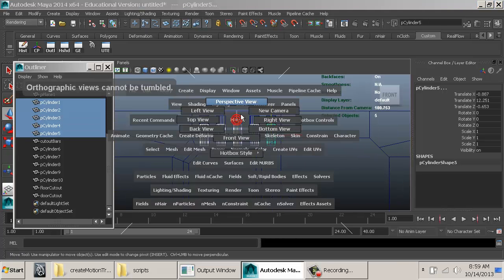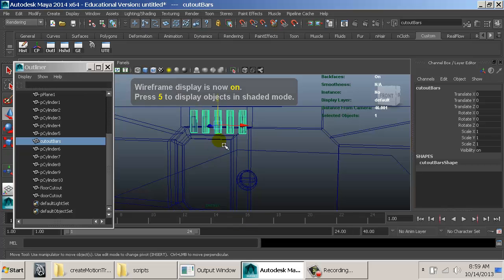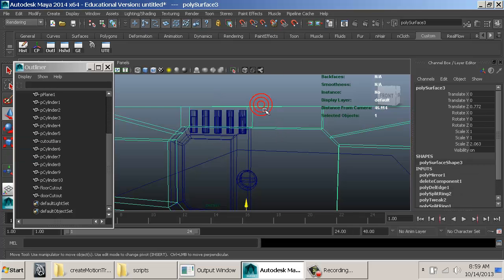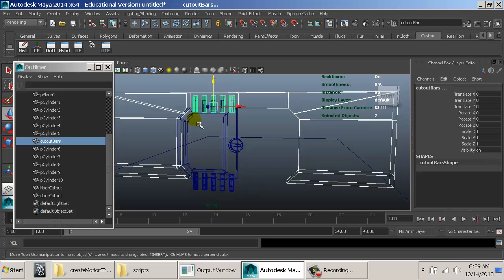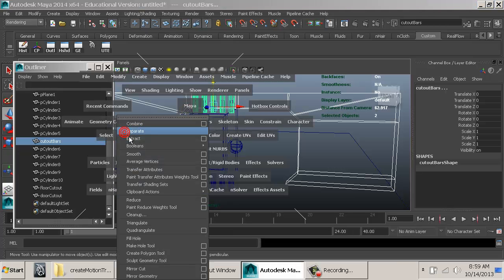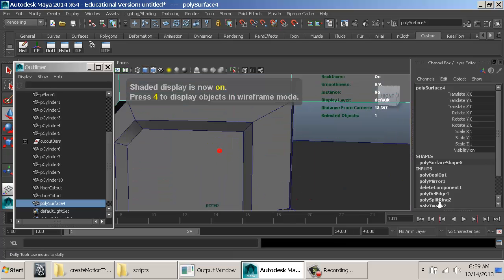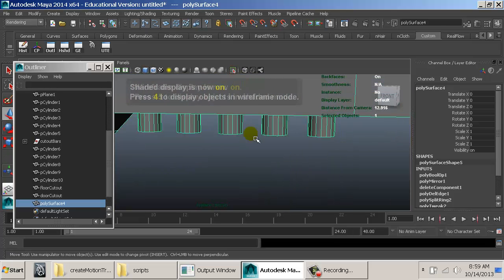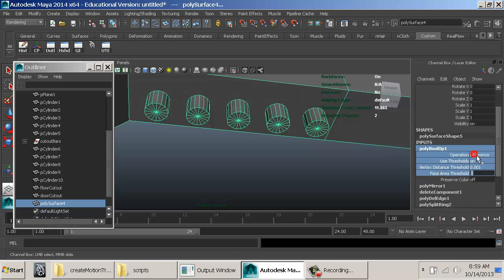Cool. Okay. And this is where the game comes in, making sure it's nice and could be something that would actually work. So I'm going to grab the door, or the wall. I'm going to shift click these, because that's my wall cutouts up here. And I'm going to say Mesh Booleans Difference. And again, it didn't do, let me go to isolate. It didn't do what I wanted. It actually stuck them out. So I go back to my bool op, I change my difference.